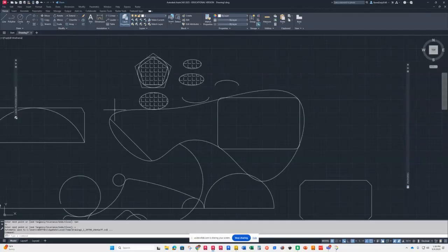And then later on, you can figure out the distance at each angle that is out from the center, or off of the base circle on a cam, and then you can finish it off by drawing a spline that will give you that shape without having to do a bunch of trimming and 3-point arcs and all that fun stuff. So it's not a tool you use very often, but you can make odd shapes or uneven shapes, like if you were doing a joystick. That's a kind of irregular shape where you can do that.